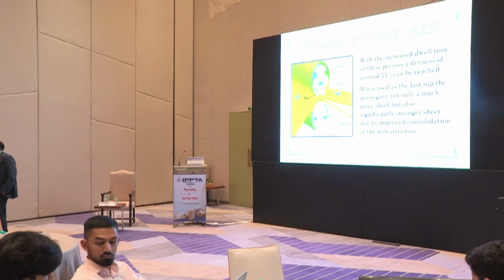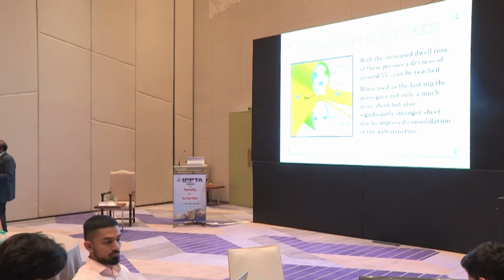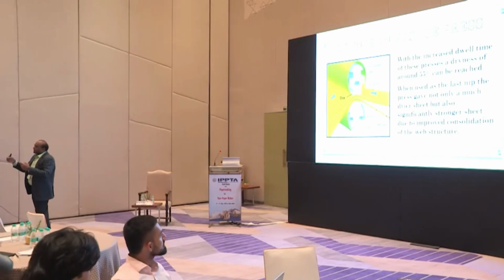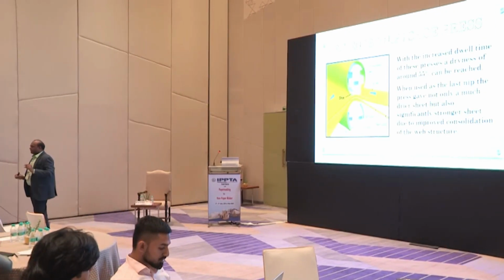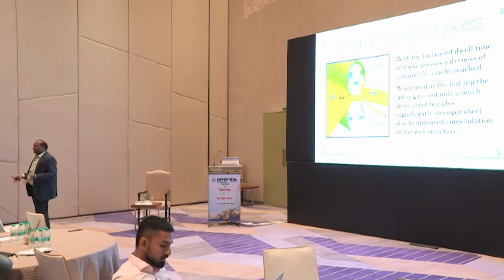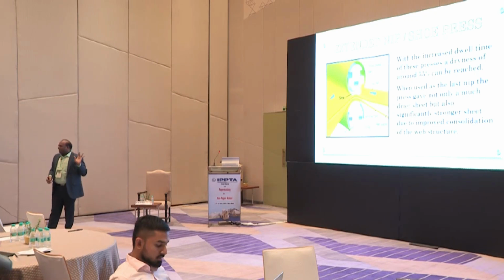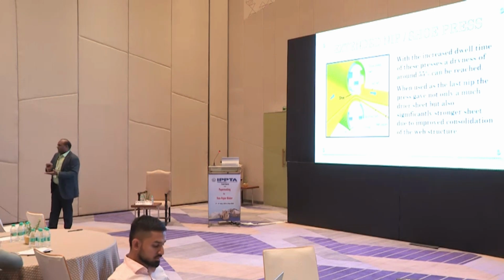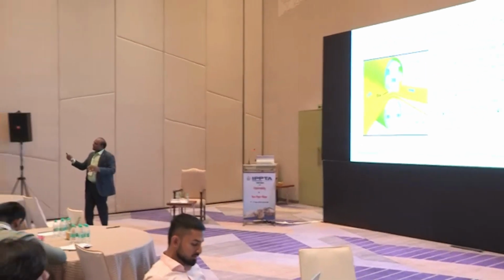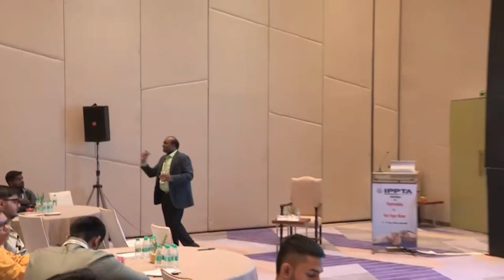Yes, bulk, in spite of bulk. Because if you are increasing too many press nips, it will reduce the thickness, the caliper of the paper. So we are going to lose the bulk. So it works in two ways: it's an economical way, whereby you can remove excess water before the dryer itself, and we can retain the bulk without affecting the quality parameter, thickness.